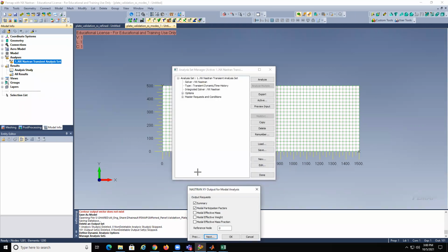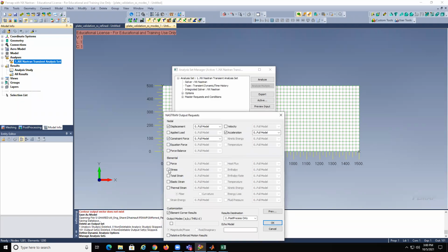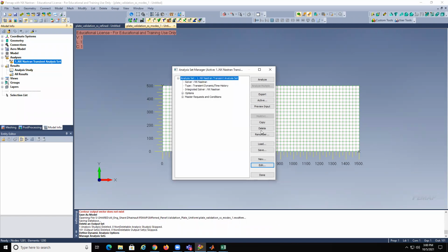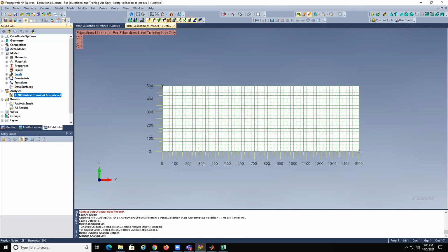And then by default, this is not going to change anything in this case. Make sure that it's also going to calculate the stresses, which here is not defined. Okay. And you click analyze. Everything else is exactly the same. Not really. You need to do one more thing on the model because it's transient. So the load is unchanged.